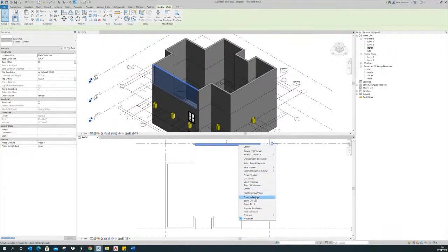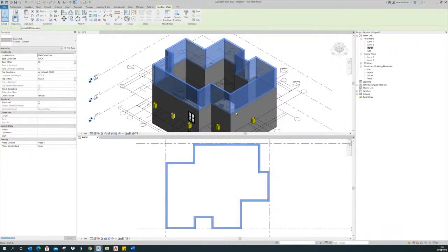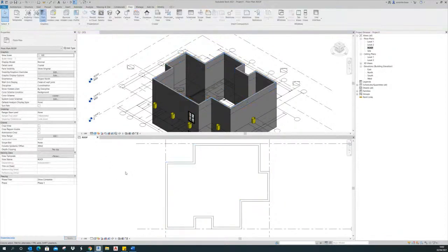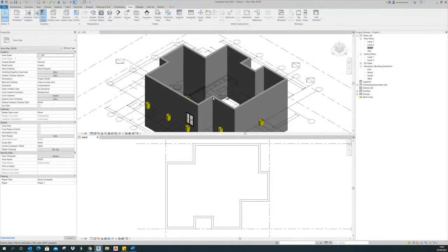And let's select again, select all the instances visible in view. Okay. And now, since these are of the same type and properties, the same wall, we can edit this type of wall. As of now, the top constraint is up to roof level, and the top offset is 4 meters. We don't want that. We want it only 1.1 meters. And then let's edit the parapet.